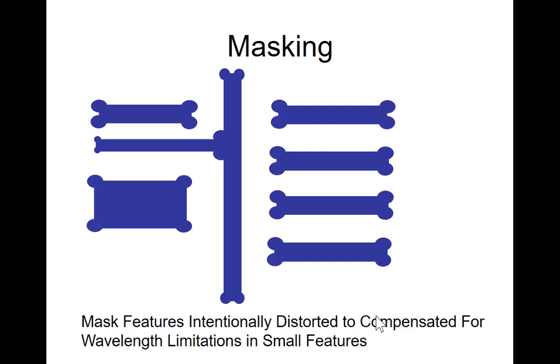Maybe around 10 years ago, they began to do what we call OPC, optical proximity compensation. Now on the mask, the cut slot is not even a straight line. You intentionally make it different. You look at the density and the proximity areas, and then you do a pre-distortion on the way that you cut.